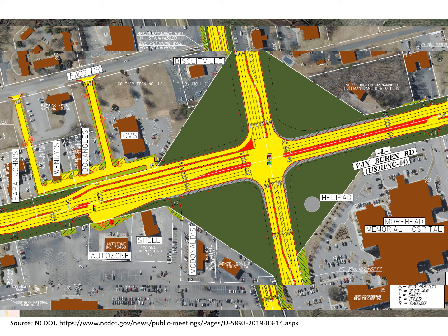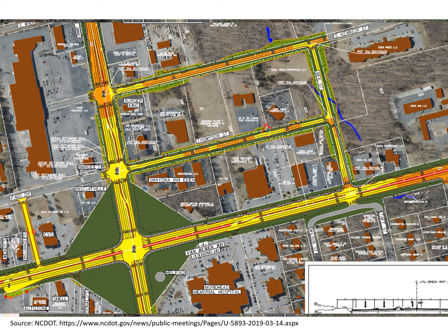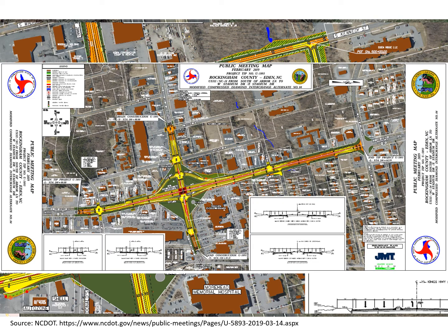The next one that we have is a CFI, a continuous flow intersection. And we'll notice the key part of this is that crossover point before the main intersection. So if you're turning left, you're going to make this crossover here, and then you'll turn left here for the CFI. Our next one is a connector or U-turn. And so this is incorporating some of those same components of a quadrant roadway. So looking at this as a network, where can some of these additional turns be made to make those connections?